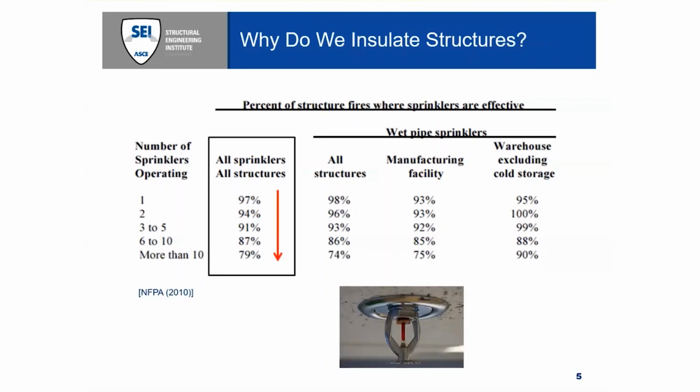So there could be cases, extraordinary events, where the sprinkler system is not effective at controlling the fire and it becomes uncontrolled. And this is where structural fire protection comes in. This is its real purpose. It serves as a critical backup safety system in those events.